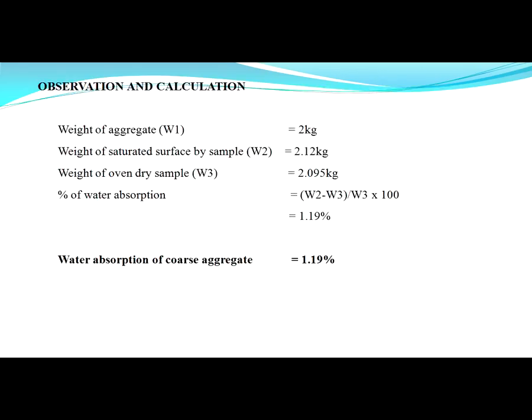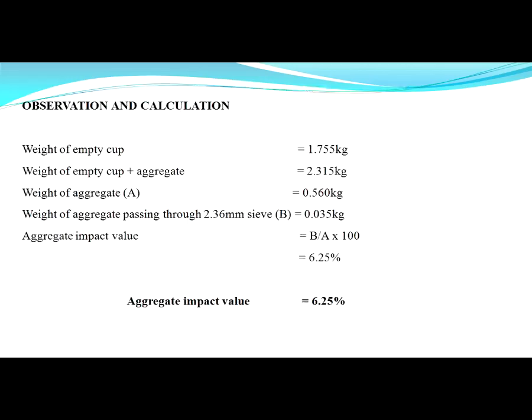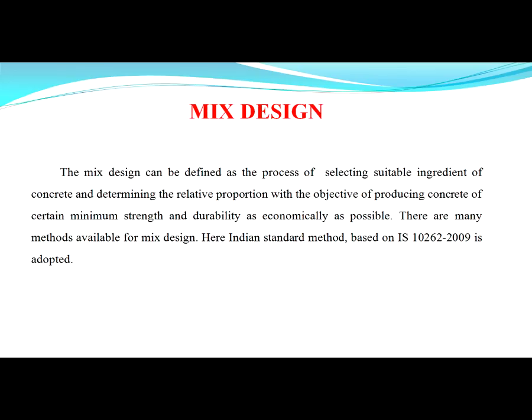By this observation and calculation, the water absorption of coarse aggregate is 1.19%. Impact test for coarse aggregate. By this observation and calculation, the aggregate impact value is equal to 6.25%. This is the mix design which we used for this project.